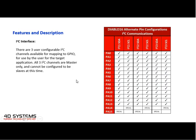You have also the I2C interface. Much the same way as the SPI, there are 3 user configurable I2C channels available for mapping, and they are also all masters only. Notice here that, same as the SPI, you can assign any of the channels. This is channel 1, for instance. You can assign it to any of these pins. Channel 2, similarly, and channel 3. Except PA14 and PA15.